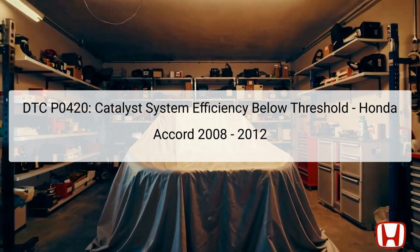The main components involved in this issue typically include the catalytic converter and the heated oxygen sensors, HO2s. The catalytic converter is located in the exhaust system, generally between the engine and the muffler. The HO2s sensors are placed both upstream and downstream of the catalytic converter, measuring the level of oxygen in the exhaust to determine its efficiency. If the readings between these sensors don't align as expected, it triggers the P0420 code. It's important to address this code promptly to ensure vehicle performance and compliance with environmental regulations.